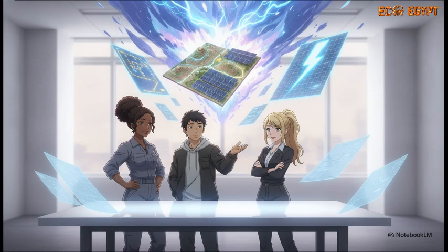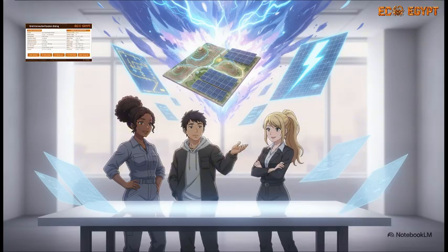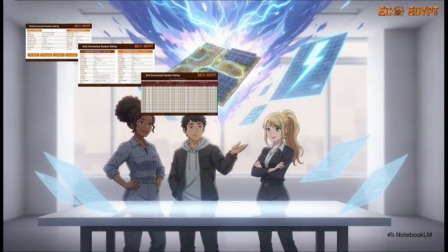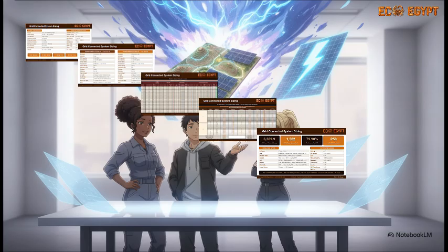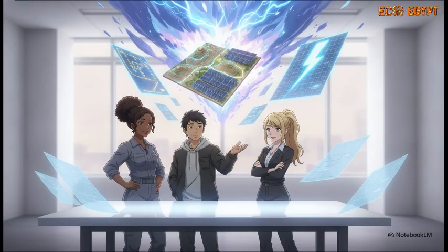It's got everything: the structural civil drawings, the single-line diagrams, exhaustive mathematical proofs for all your cable sizing and voltage drops, the rigorous PVsyst yield simulation reports, life-saving earthing and lightning protection layouts, every single component datasheet, and a massive line-item bill of materials. The whole shebang is in here. A complete design really is a rigorous, undeniable body of evidence.